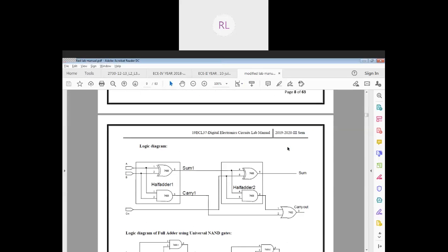Fine. So further, this is actually simplified. If you can see here, your ABC in plus C in bar, then again plus C in AB bar plus A bar B. So this part, I will be taking as your XOR function. So that is what I have done here.